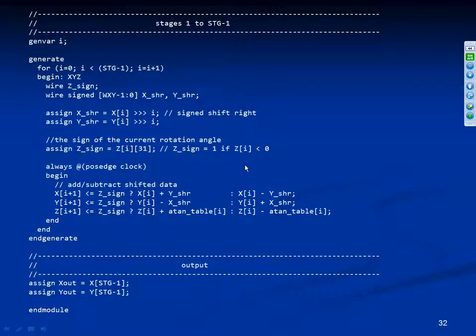I don't know what the actual error of this one is versus the one that's in SVN right now that's called CORDIC.v. If you look at the one called CORDIC.v, you'll see that it does do some rounding. So if numbers are negative, it does one thing, and if they're positive, it does another. But basically, yeah, it uses a bit just below the last one that you'd normally be using to do the rounding.